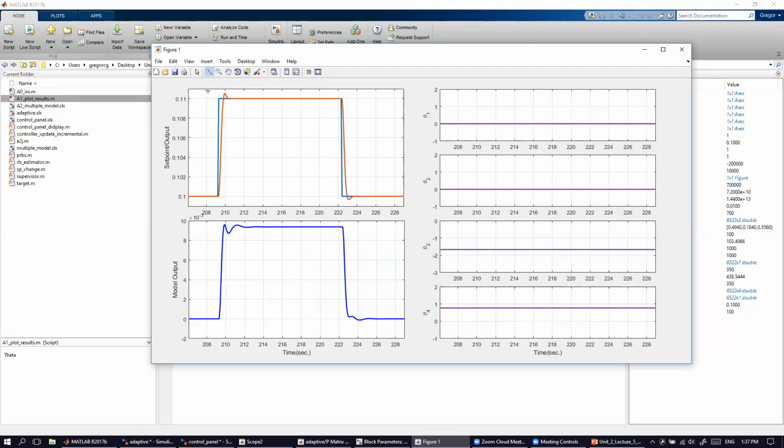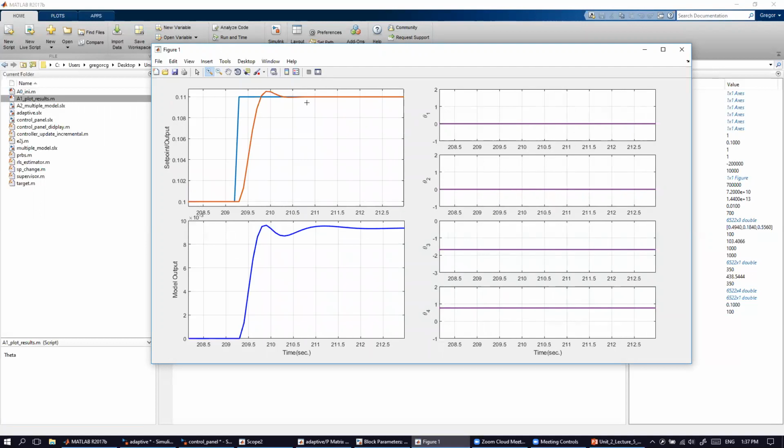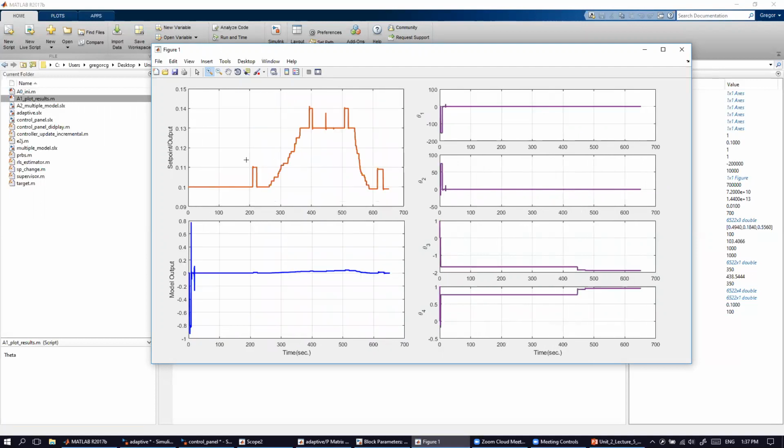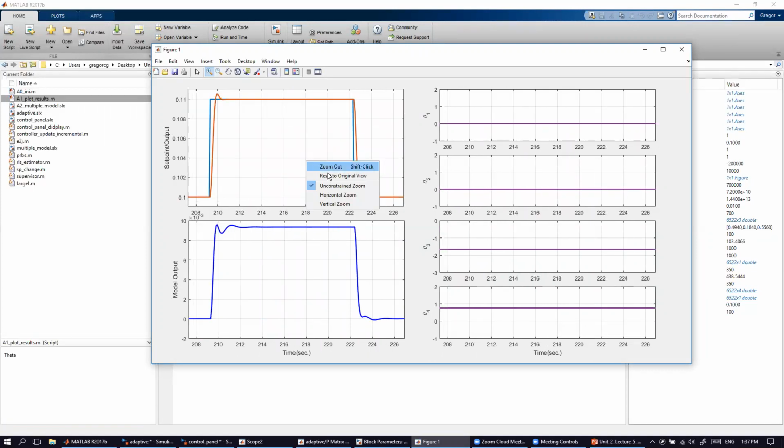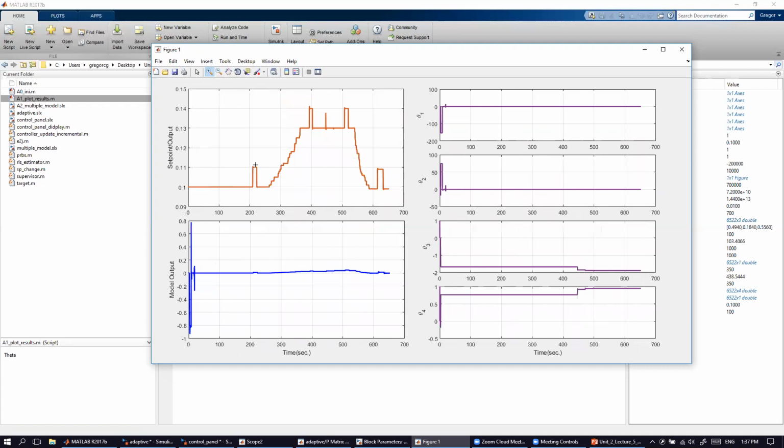And now our automatic controller tuning provides us with a controller which gives the closed loop response as we want it, like this. We're happy with that here. Then the adaptation was turned off and we moved the system to the higher operating point, and we did the step test again.